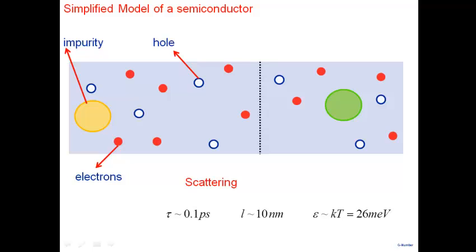But otherwise, I'll have all these positive current, negative current, positive current. So all these semiconductors that you see here, when we talk about currents, we are talking about average current. But this average current is sitting on top of an underlying random current. All right. So this is the source of noise. Okay. So my average current is 0, but I have a noise component here. Okay. So keep that in mind. Although in this particular course, we are not going to talk much about noise, you see in the inherent randomness here that there is noise in my system here. Okay.